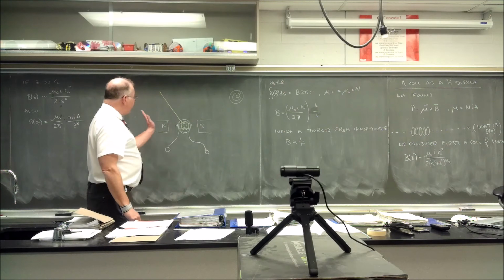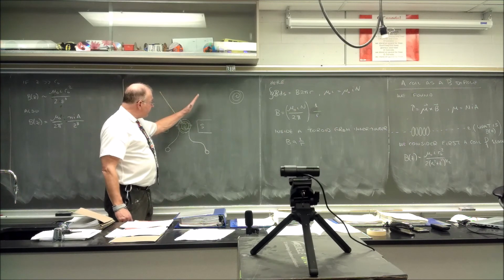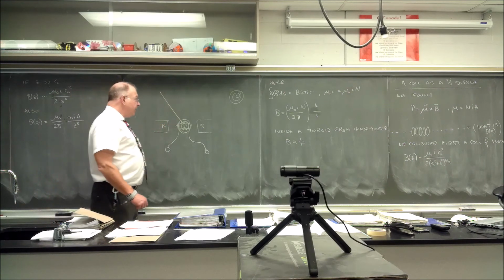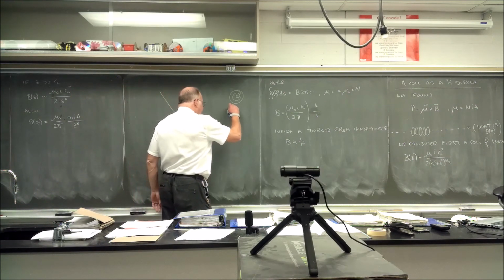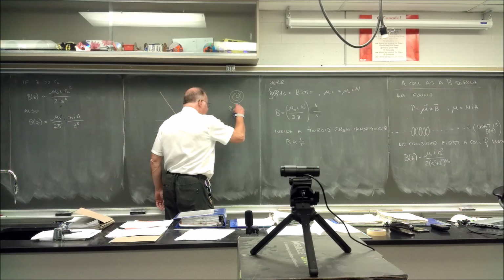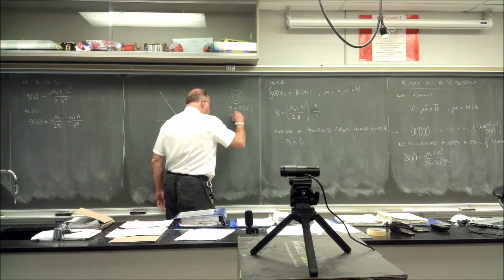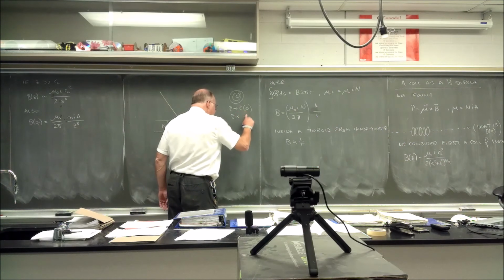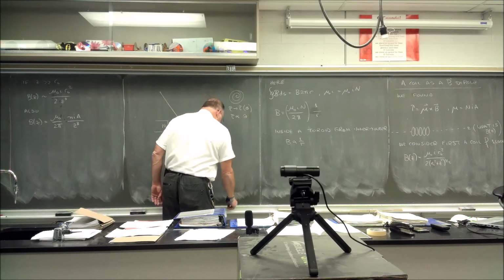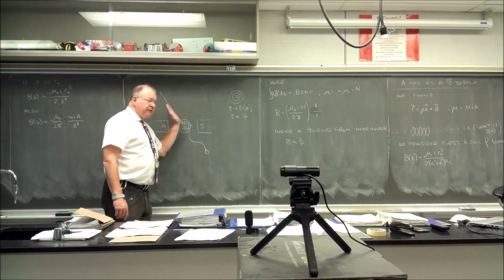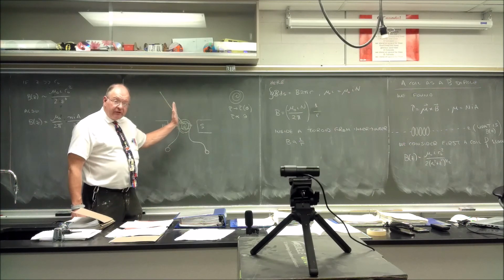So as the meter rotates like this, it winds the watch spring slightly. Now this watch spring, the torque is a function of the angle. And this torque is linear to the angle in radians. So what that means is, just like a compressive spring, as you continually rotate it, the force, the torque if you will, gets increasingly greater.